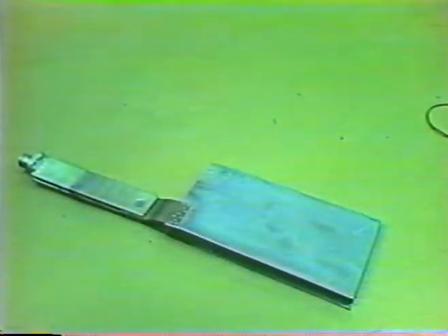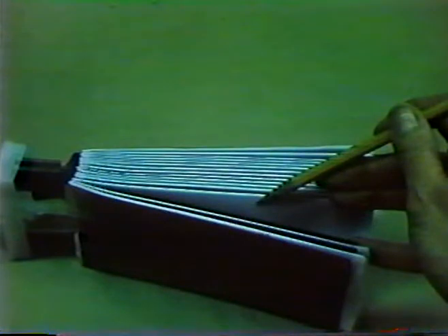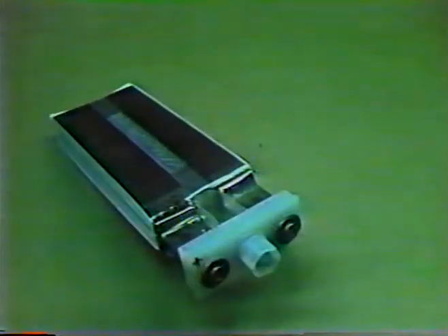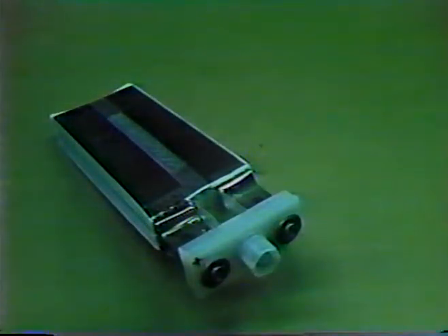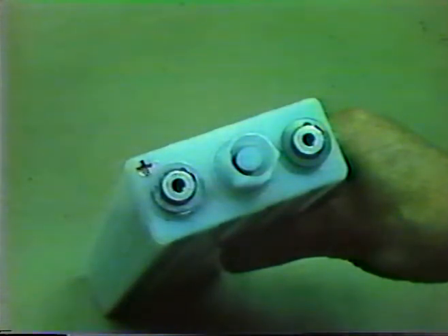Nickel tabs are welded to the corner of each plate, and the plates are grouped into core assemblies. The positive and negative plates are sandwiched in a multi-layer between special separators of fabric and plastic. This stack-up is bound with a plastic binder to form a compact assembly. A cover and vent assembly is attached to the plate stack-up to provide a foundation for the cell, and the filler cap allows for servicing and venting. A polystyrene or nylon case houses the cell.